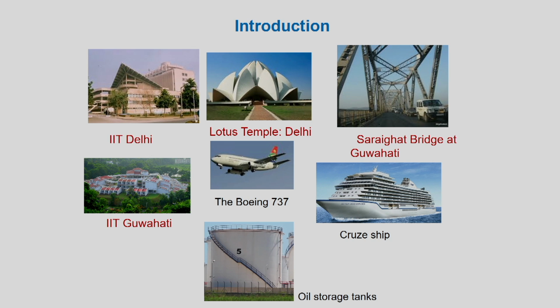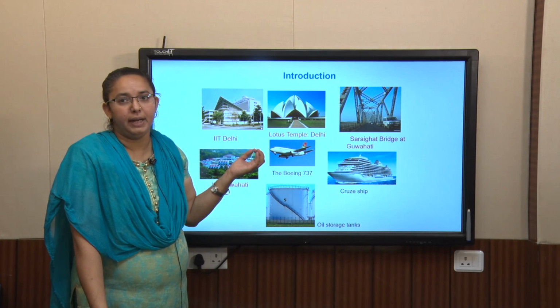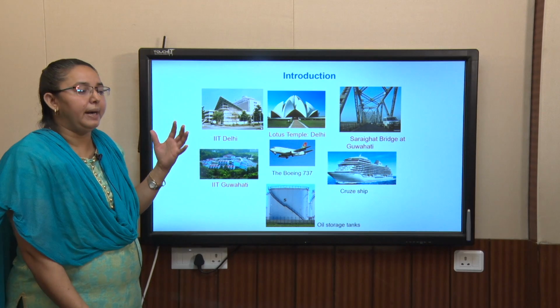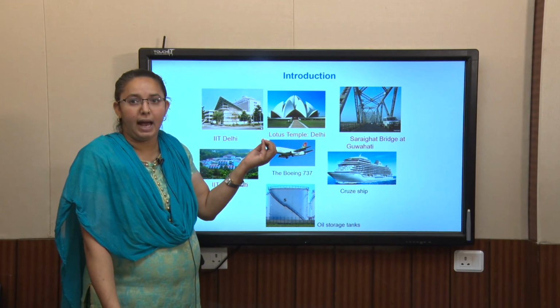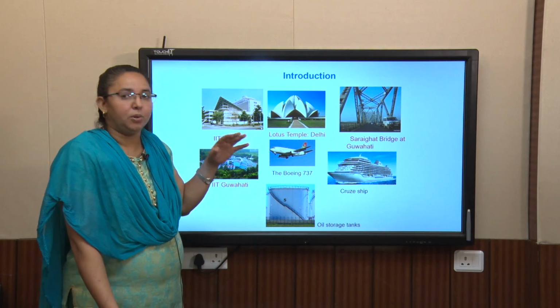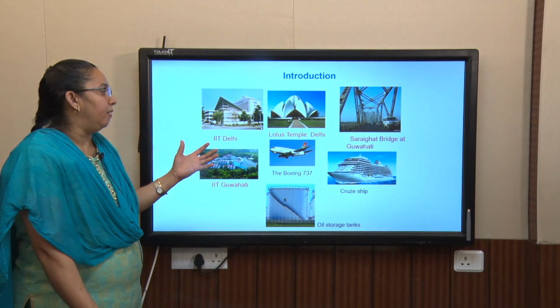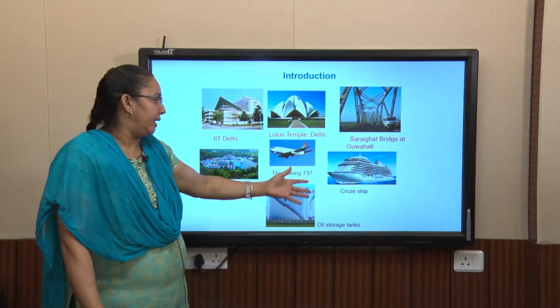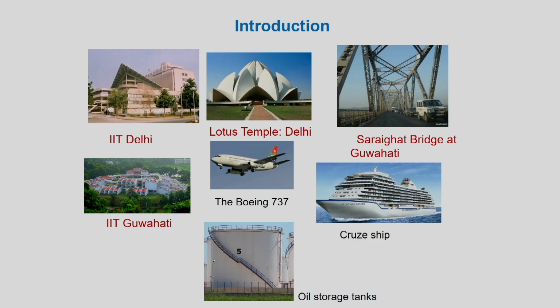If we divide all structures into small elements, they will be either a beam, a plate or a shell. So, any structure, any machine, any component can be subdivided into 3 basic elements: beam, plate and shell. If we are able to predict the behavior of that basic element subjected to different kinds of loading and different kinds of boundary conditions, definitely we can analyze these structures, because these structures are made up of these. So, applying the continuity conditions or some relevant assumptions, we can analyze these structures.